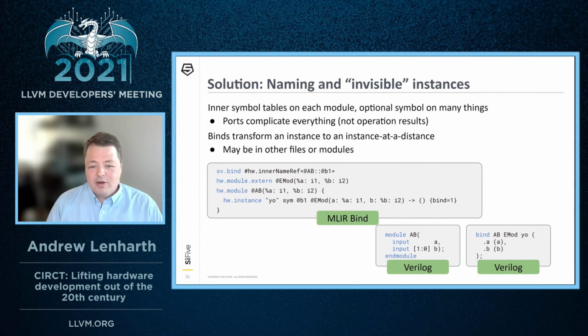The other thing Verilog has that's used extensively is basically action at a distance, but for instantiation. You'll want to say, I have this module I want to test. I'm going to put all my debug code in a different module, and I will instantiate it in the thing I'm testing and pass all the signals I want into it so I can monitor it remotely. But I don't want to put that in the module, because that would be modifying my original code and having stuff that isn't actually going to be synthesized.